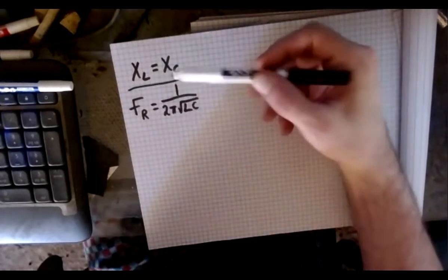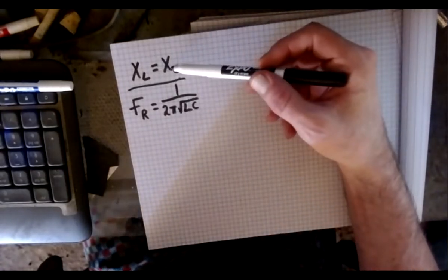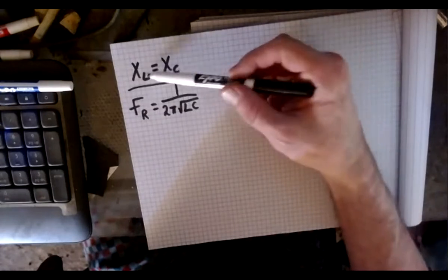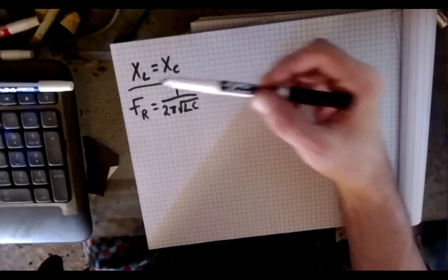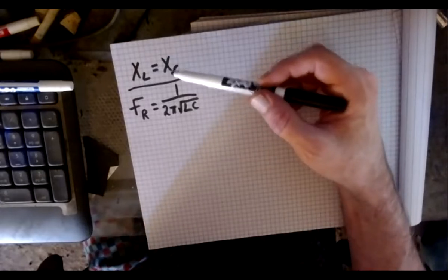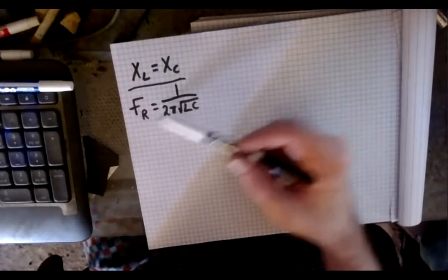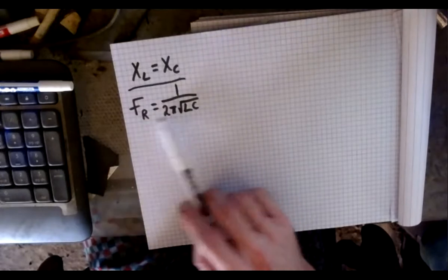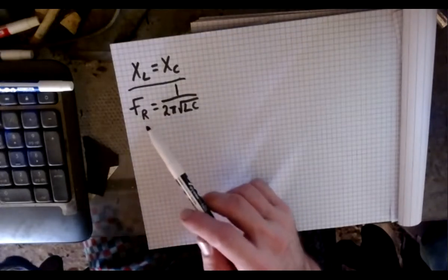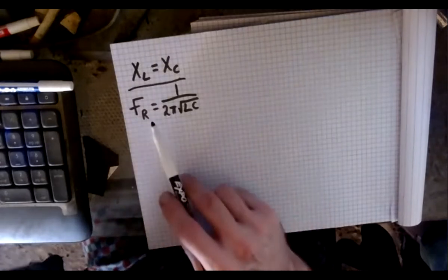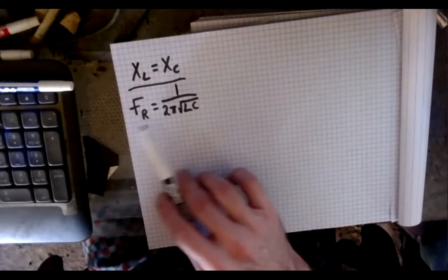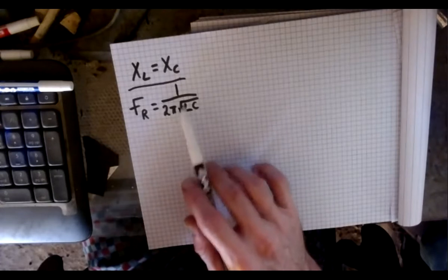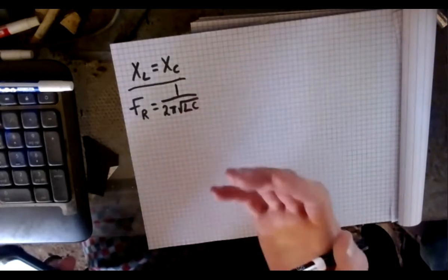And this is derived from this statement right here. So basically we pull it all out, to 2 pi FL is equal to 1 over 2 pi FC. And if we go through and juggle it, what we come up with is this formula right here. So this, I hope we know, sets my ideal resonant frequency based on the components of my circuit, okay?